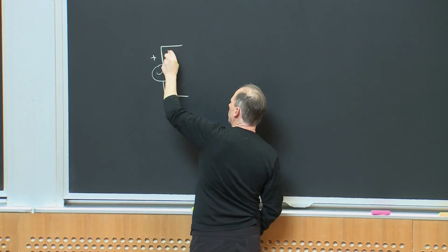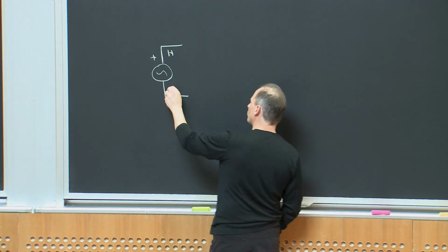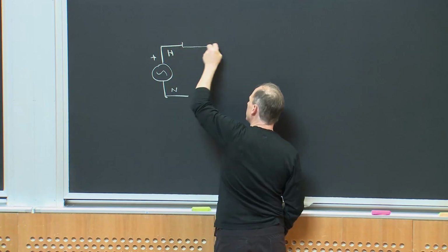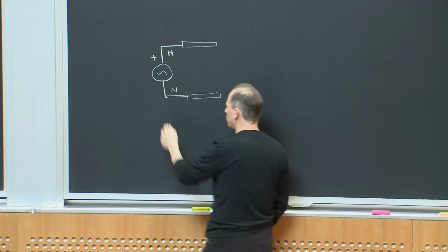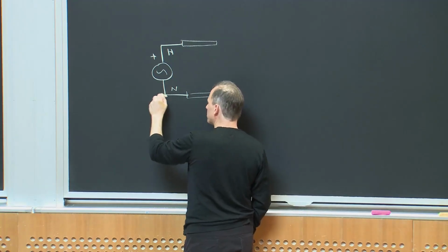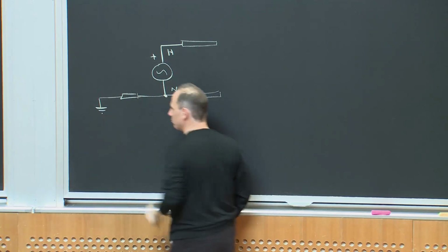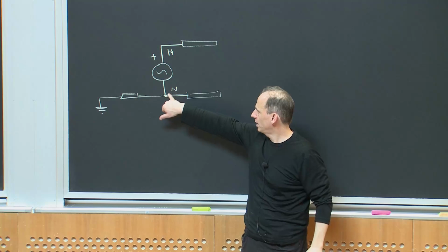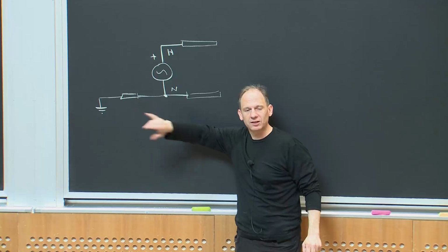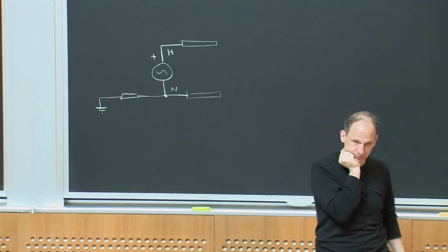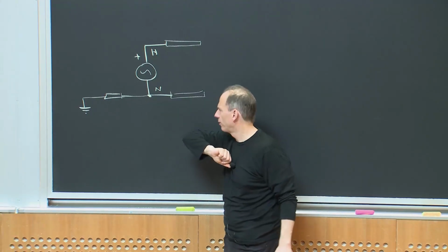And I have the hot terminal. That's the black wire, right, running around your house. Black is for death. Don't get near that. You have the neutral wire, which is usually white, okay? And you're going to carry some cabling inside your walls, hot and neutral, okay? And I should say that neutral, back at the service entrance somewhere, tends to be tied to ground, right? So the neutral is going to be near ground, but it doesn't actually have to be precisely at ground, okay?